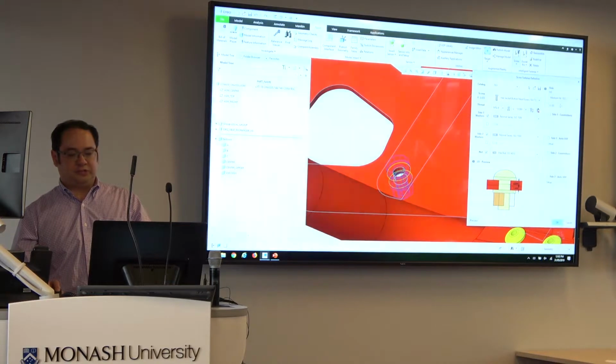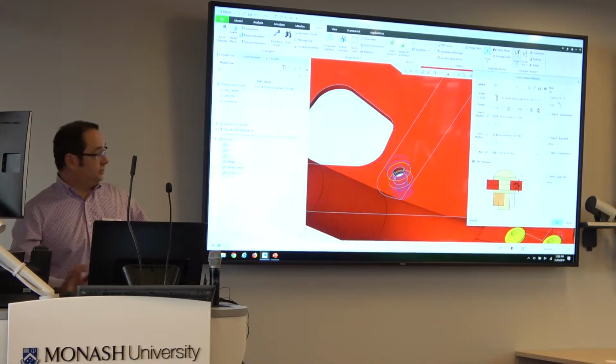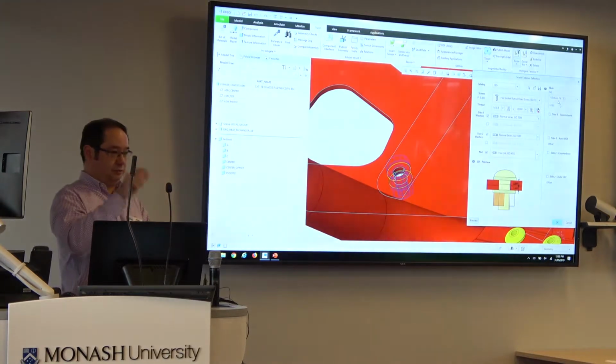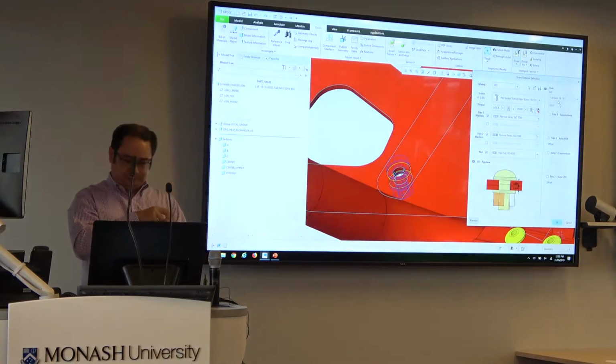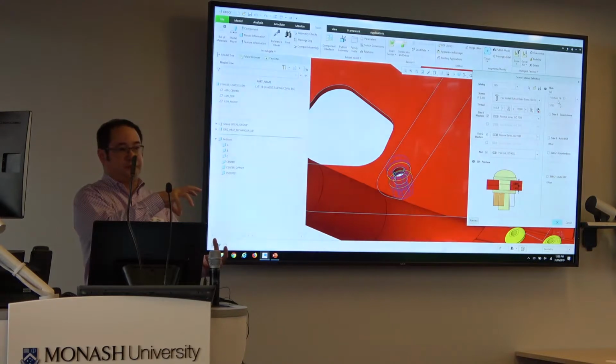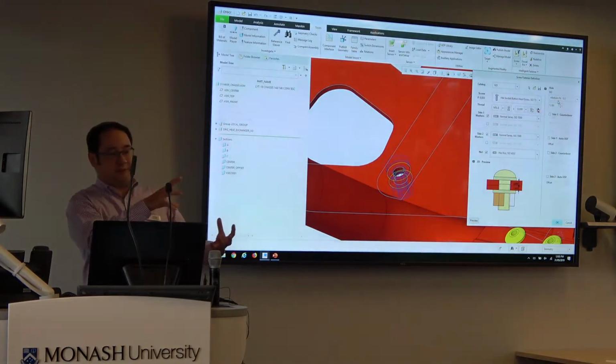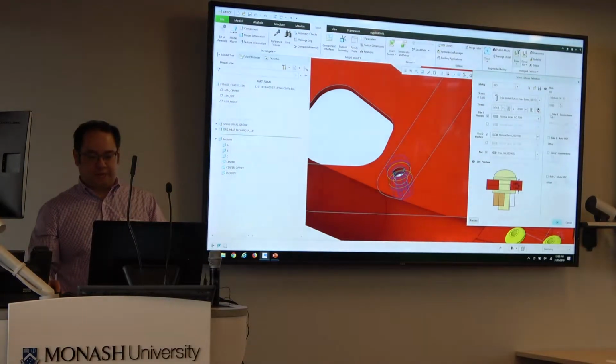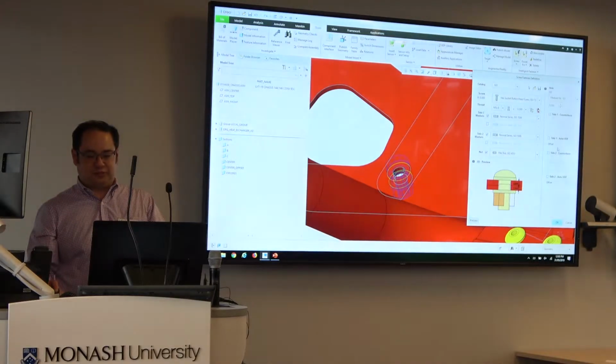I've also got my options here. In this particular case, the holes are already there, but I could just pick a point or an axis or just do a mouse click, and that will automatically create both those holes for me, okay? Drill all the holes, do the tapping if I'm doing a tapped hole for a screw connection. I've got options here for whether I'm going to put a counterbore in or not, although my geometry is a bit thin for that, and I'm just doing some sheet metal. So I can go through all of those options there.